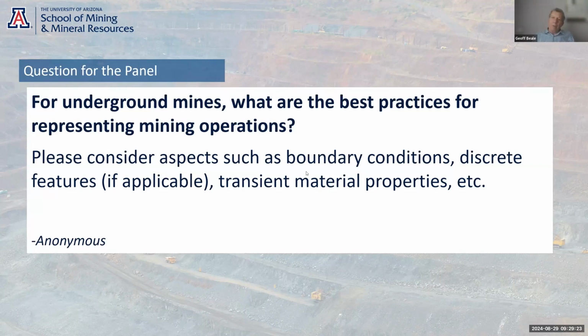There was a mine I worked at early in my career, which was making about 1,500 liters a second, i.e., lots of water. And before I had the experience to think too much about exploration drill holes, we were all trying to deal with it underground. And it wasn't until that mine closed and the groundwater system completely recovered in about 12 months that I realized that all the water was going down exploration drill holes. So it's something that I personally have learned from hard experience.